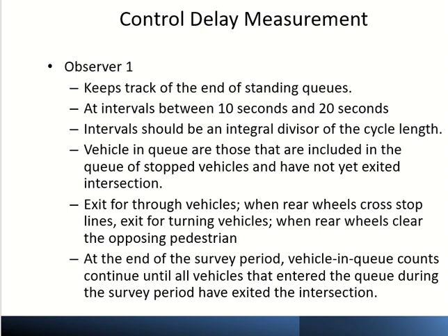Okay. The rule is very simple. If the vehicle is going straight, if it is after the stop line, it's not in the queue. If it is before the stop line, it is in the queue. Okay? He cannot say that, okay, this vehicle was moving, so it's not in the queue. No, it's moving, but it's part of the line. Okay? If the vehicle is going straight and it is behind the stop line, it's in the queue. Okay? Yeah? So this is for straight.